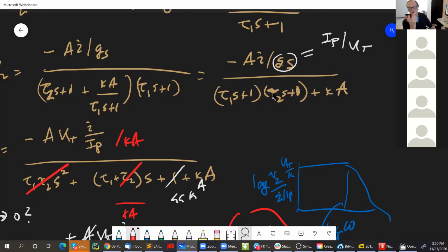And so your exercise now is going to be split over. I'll talk about it again next week, but basically you solve for those roots. You can plot the root locus plot and you can understand the behavior of the circuit as you change, for example, the bias circuit, the bias current driving it. Okay, so I hope that's helpful. That's kind of an introduction to second order analysis of a circuit like this. It's the same thing you do for any such second order system. You'll find that it has much more richness than you might expect. You know, people spend long time trying to really grok this stuff and get intuition about it.